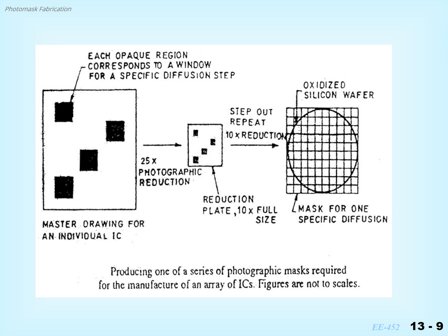Okay, now what is a photo mask? A photo mask is a stencil sort of thing over which the circuit layout has been made. I've told you that it is transparent in certain regions and opaque in other regions. Usually the master design is made very big in size. After that, we reduce it photographically around 25 times, so that it can be projected and repeated over each IC on a wafer. So this is how the mask is designed.